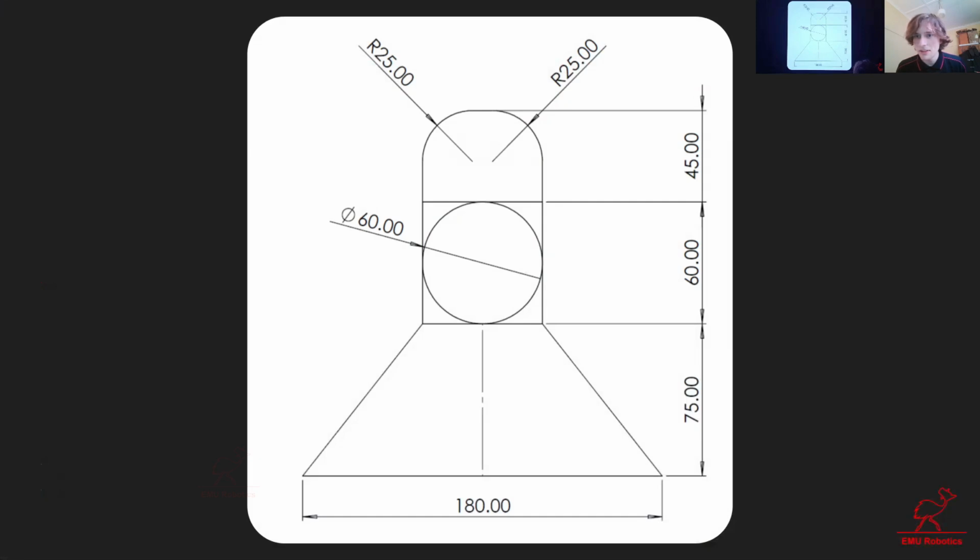What is that? Is that 180 centimeters or 180 meters? No, it's millimeters. In engineering, especially in these sort of engineering drawings, every single dimension, unless said otherwise, will be in millimeters. If it's a very nicely done drawing, they might even have a box in the corner that actually says that.